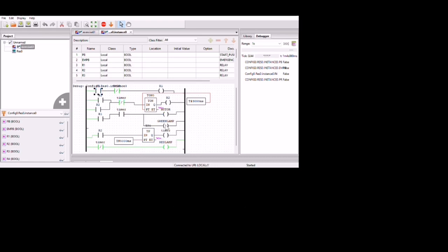After that we click the push button and it will count 3 seconds to turn on the motor and green lamp, and then it will count 5 seconds and the motor and green lamp will shut down, and it will repeatedly continue as we have to apply the looping sequence.